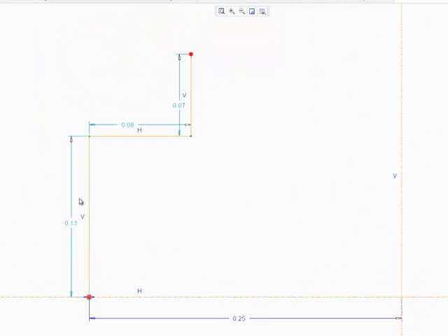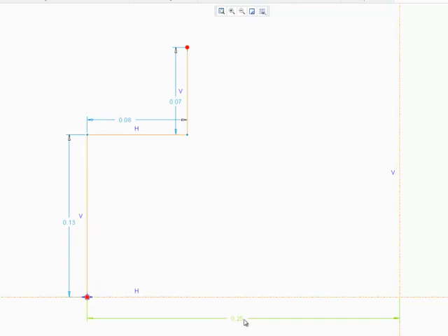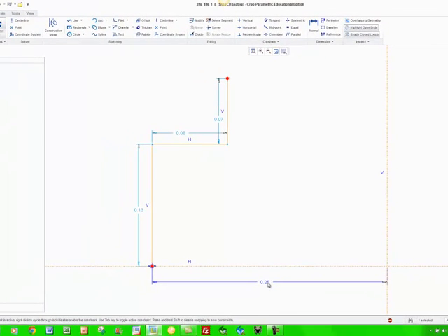It's always good to edit. And you'll see the color has changed. So now instead of a light blue, it's a dark blue. So if you notice, I can still change this dimension, even though I had personally changed it. So if you want to keep that from happening, you can click on the dimension, hold the right key, and hit lock. And now you can see it's red.